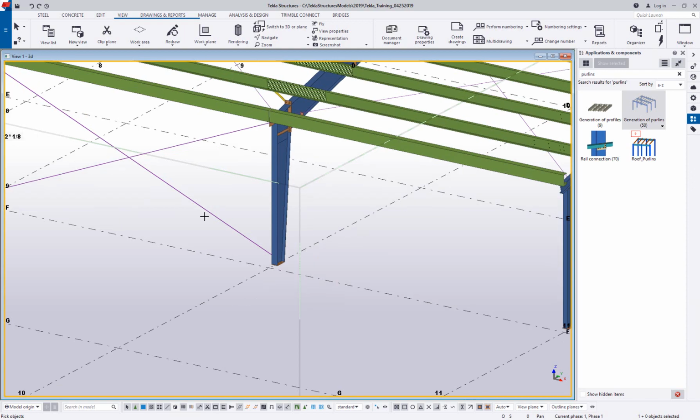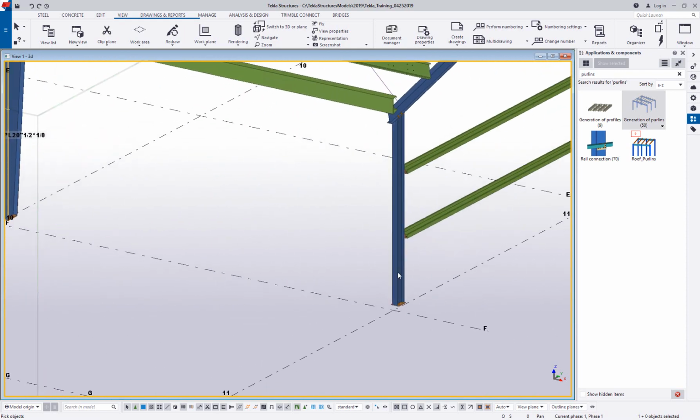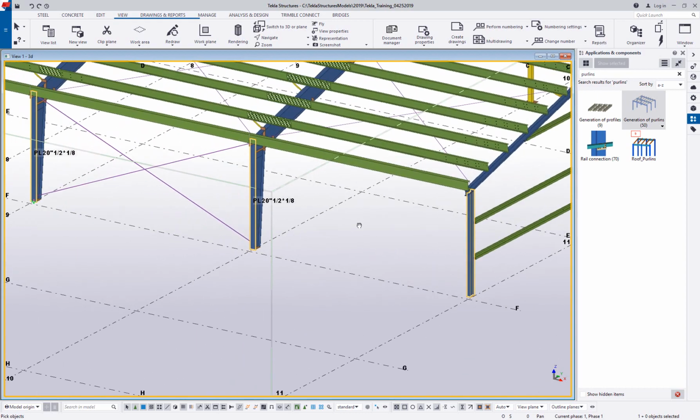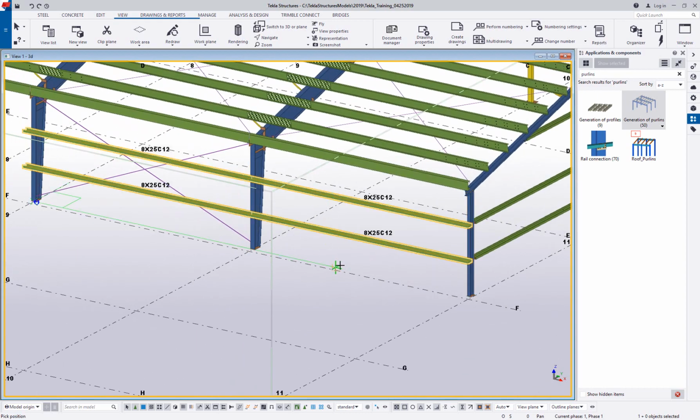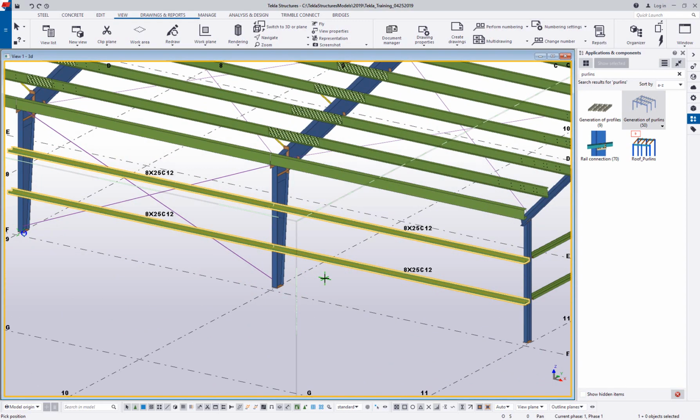Where do we want to measure from, and then what pieces we want these to frame to. So in this case, I'm just picking the flange plates and then this wide flange column at the end. And when I middle mouse click, it'll go ahead and create those very quickly for me with the breaks at each intermediate member at whatever spacing I've defined. So just one more nice tool to be able to very quickly recreate some framing or set up new framing from the original MBS buildings.